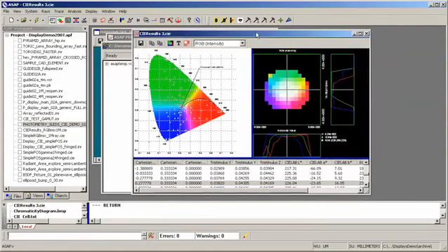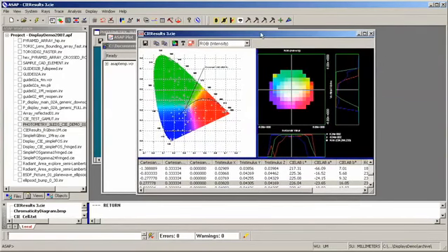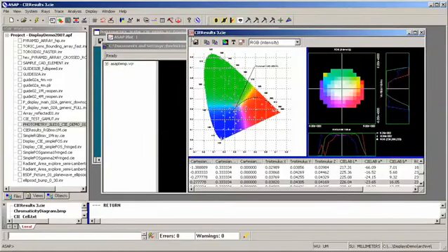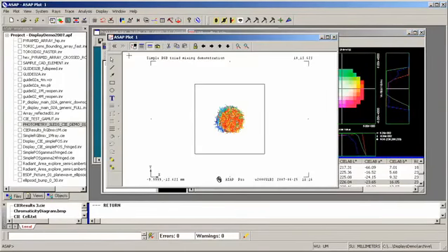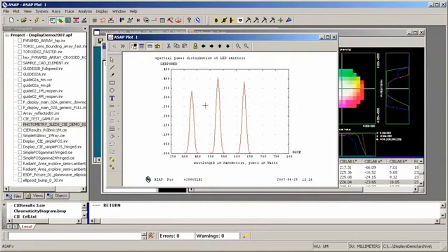And we have a CIE analysis window here with the mixing results. Before I talk about that, let's just go through some of the other graphics very quickly. First, this is the actual spectrum of the 3 LEDs. You see that they are well separated in wavelength. We're roughly centered on 425, 525, and 625 nanometers, give or take a bit. And the powers are comparable, but not exactly the same. They're very similar, but not exactly the same.